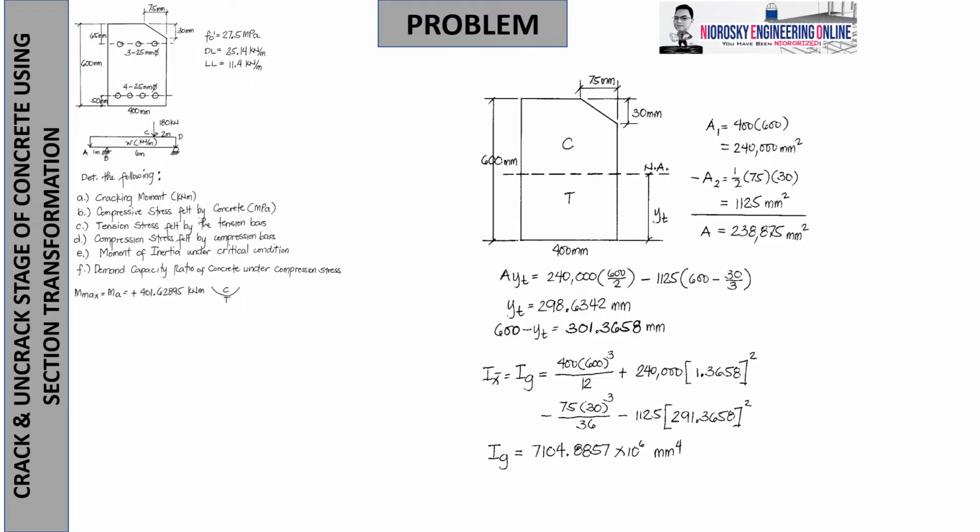Also learned from statics, I need to get the inertia about the stronger axis, I bar x, since this is the moment of inertia about the x-axis. I bar x will now represent the gross moment of inertia where reinforcement is neglected. So by this, I think you're aware that I can do it this way. Everything is projected to the neutral axis. I assume that there is a full rectangle, followed by deduction of this triangular area.